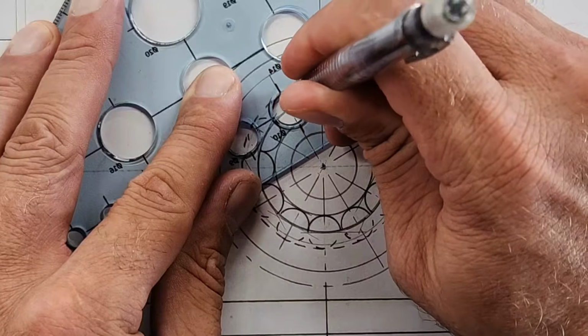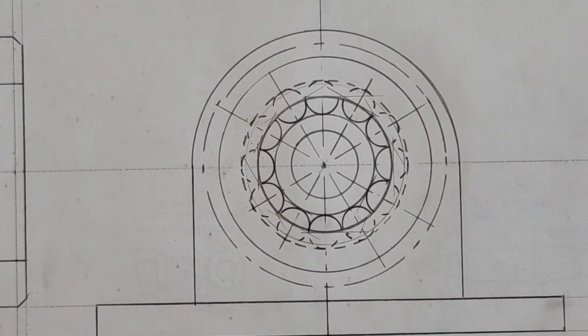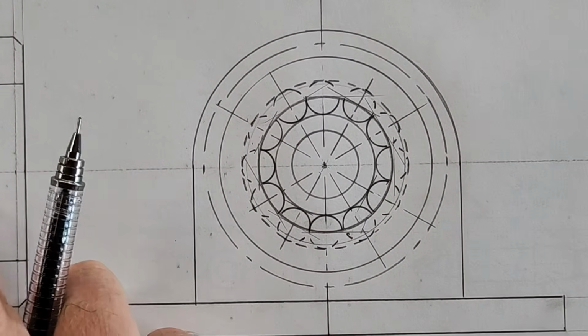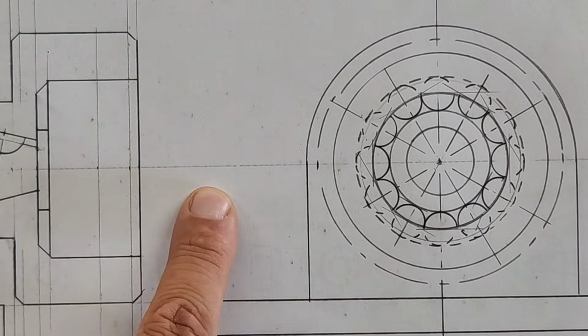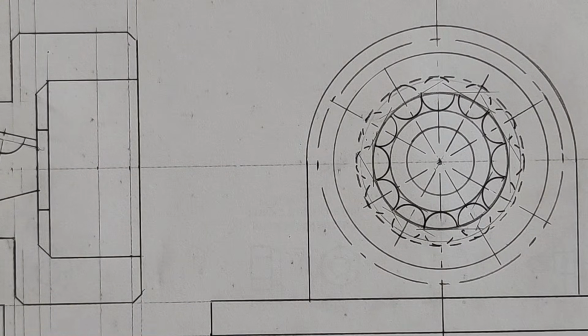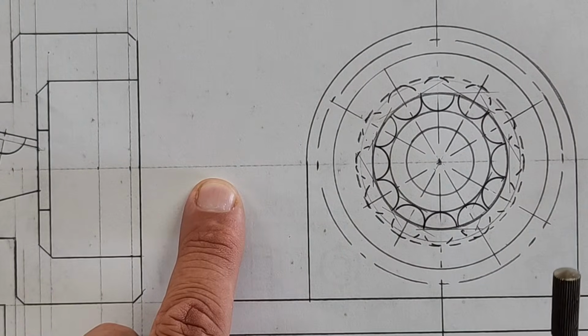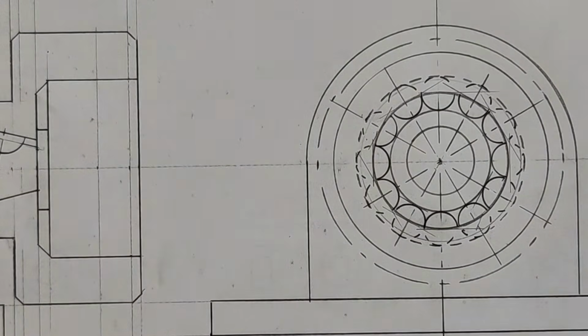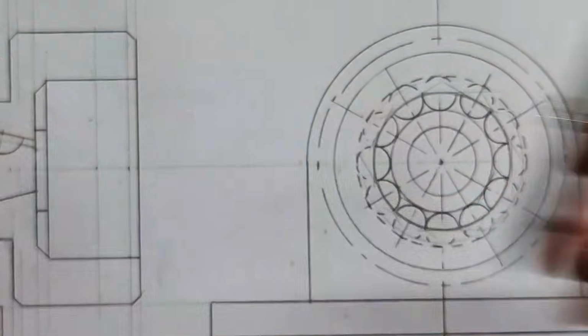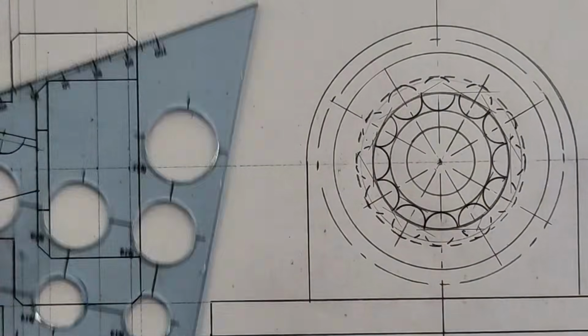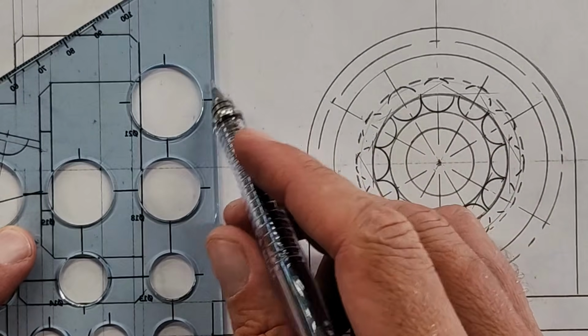Okay, I want to quickly go to be able to draw our nut on the left hand side, on the front view here. I need an auxiliary view. You can draw that auxiliary view anywhere. Maybe we should draw it outside here because it is quite a lot. So it is M12. What is 12 times 1.5? It is 18, so that means 9. That's your radius. Radius 9.